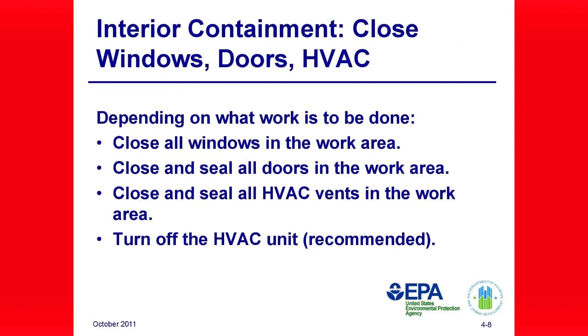Interior containment. Close windows, doors, and HVAC. Close all windows within the work area. When conducting window replacements from the inside, consider attaching plastic sheathing to the exterior of the window to prevent spread of the dust and debris to the ground or other surfaces under the window. If window replacement affects both interior and exterior surfaces, then set up containment both in the interior and exterior.